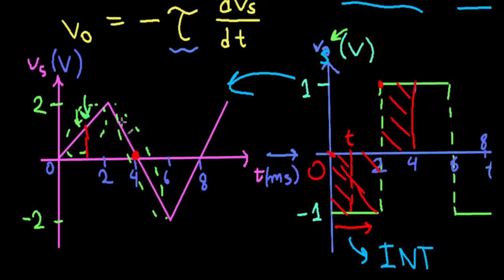This is going to be the output now. The value of the output voltage at 4 milliseconds is 0. As you can see, it goes down because you built up an area which is actually negative, and it was negated here. You built up a certain area with a certain sign, and then you're going the opposite way. You're taking in positive area, so they're canceling until you reach 0, so it's decreasing. Then the area is going to increase in a positive sense, but that value is negated, so you're going down here. I think you get the idea.